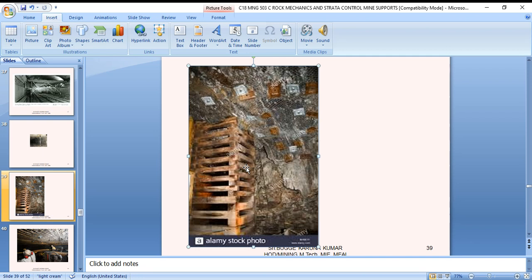In some cases, the chock is erected between four corner props. Such corner props are generally not necessary except where the roof is very bad, at edges or at the junction of galleries, and if the floor is steeper than 1 in 5, where corner props are erected. One sleeper of the chock is always placed outside the prop. Withdrawal of the member helps the dismantling of the chocks. So these are the better chock ways where erections are going on.